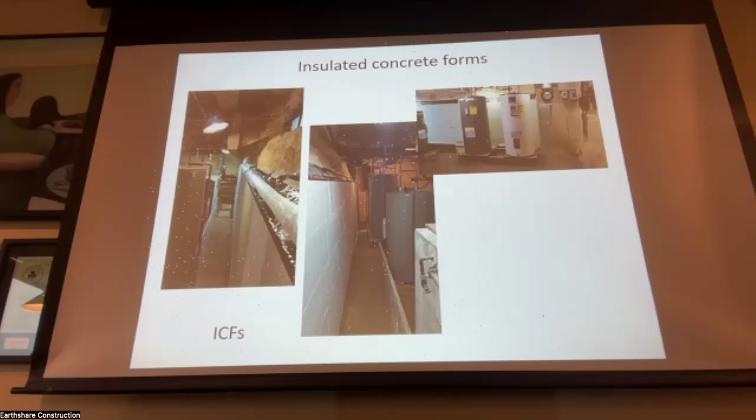We always required anyone with a rubble foundation to make sure it was structurally sound. And that means pointing is required. If it was really falling down, we didn't want to be in there anyway. Of course. I think it's a common sense question in terms of when does it make sense to put the structure at risk. And you don't want a callback because the foundation fell down behind your foam.